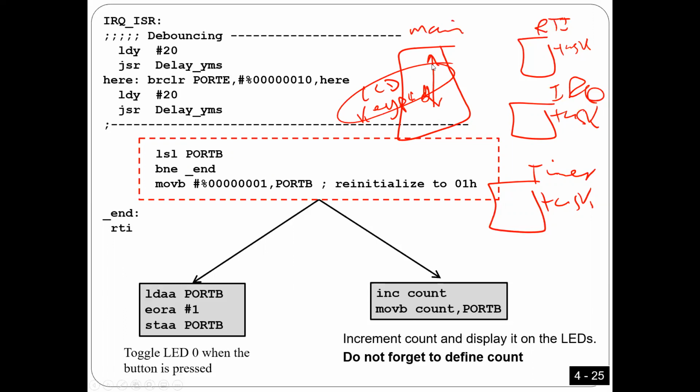Another thing, I want to use 7 segments, so I need time multiplexing, as I explained before. I can put time multiplexing here. Is that okay, guys? Also, when I press a button, it needs periodic action. That's what I'm going to teach in this chapter as well. I'm going to repeat some programs I did in chapter 3, but I'm going to move these programs from the main to an interrupt subroutine, so I can put time multiplexing here so that the LED can work.